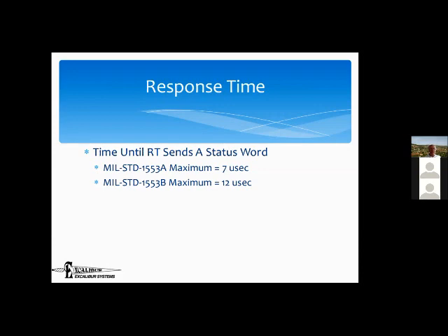Now, that doesn't mean that after 12 microseconds, the bus controller automatically gives up, because there's a certain latency on the bus, right? Even if it takes not a lot of time, but certainly tens of nanoseconds, maybe hundreds, for the command word to get from the bus controller to the RT.